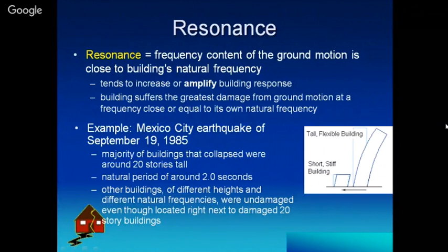And as we move further away from the epicenter, there is a dissipation of waves, the wavelength increases, and we have a reduced frequency. Suppose we have large multi-story buildings, their frequency is low. In that case, there will be resonance for the higher buildings, and there will be more damage to the buildings which are higher and which are at a much greater distance from the epicenter.